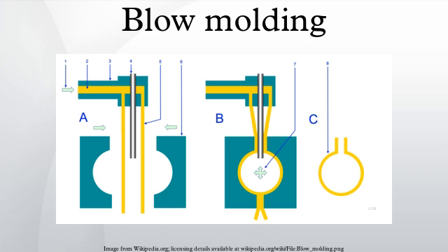With continuous extrusion, the weight of the parison drags the parison and makes calibrating the wall thickness difficult. The accumulator head or reciprocating screw methods use hydraulic systems to push the parison out quickly, reducing the effect of the weight and allowing precise control over the wall thickness by adjusting the die gap with a parison programming device. EBM processes may be either continuous or intermittent.